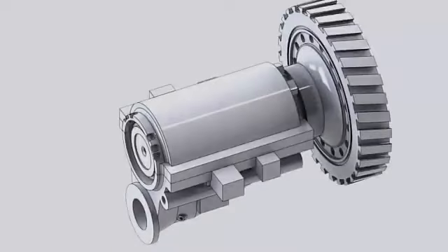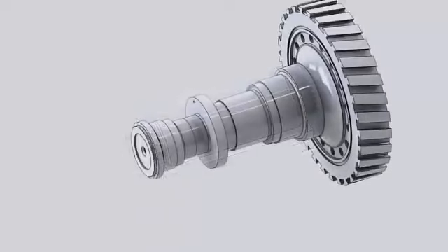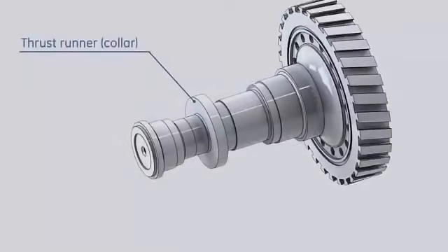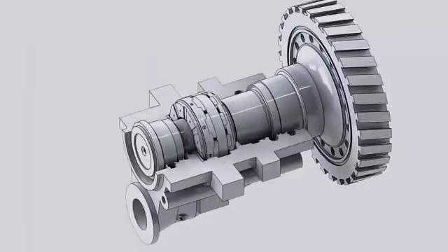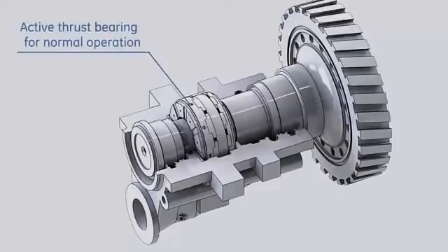The thrust-bearing major components are the thrust runner, which is integrated in the compressor rotor forward stub shaft, and two thrust bearings. During the normal operation of the gas turbine, the sum of axial forces induced by the airflow on the compressor stages and the hot gases flow through the turbine stages tend to move the rotor in the upstream direction, so that the active thrust bearing is located on the forward side of the thrust runner.